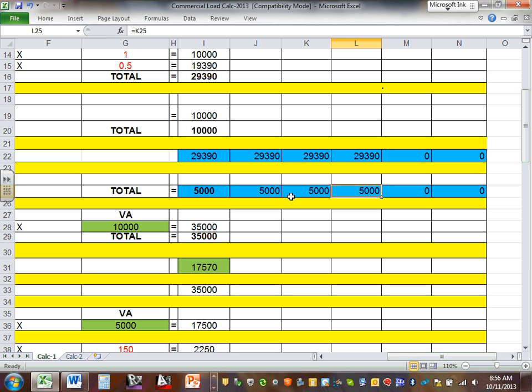I can't emphasize enough, guys. First, you do the number of receptacles multiplied by 180. Add them up. Demand them. First 10, leave them alone. Higher than 10, cut by half, add them up. Then you have to compare them with the 1 volt ampere per square foot from the NEC code book.